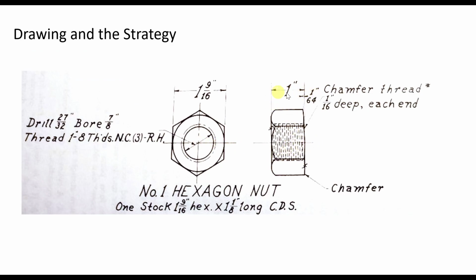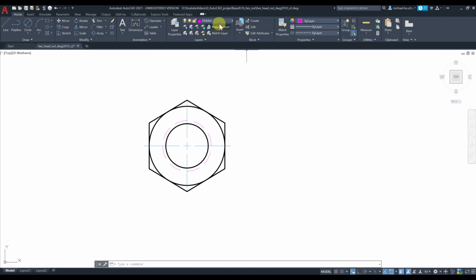I know the height of this nut is 1 inch, so let's go ahead and draw a rectangle for it, and I'm gonna change the layer to viewport. This is the layer that wouldn't print. I'm gonna use it to draw my construction lines. There's a command called ray. You just type ray, press enter. What it does, it draws an infinite line along one direction, any direction you can put. You can press F8 to draw horizontal or vertical, or in this case it's tracking the object snap.